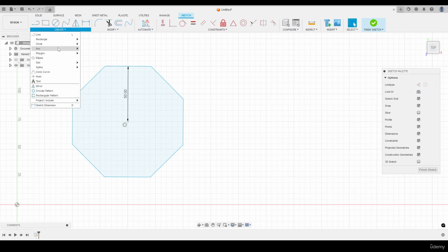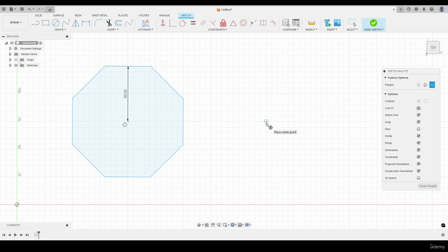I'm going to now change and move on to the inscribed polygon. Take a look at this. So I'll left click once, again, that's starting the center point. And then as I bring the polygon out, we can now see that the circle is on the outside, and every corner or joining point of our polygon is then in contact with the circle, and the edges are no longer tangential. In this case, again, we have 2 parameters to define.